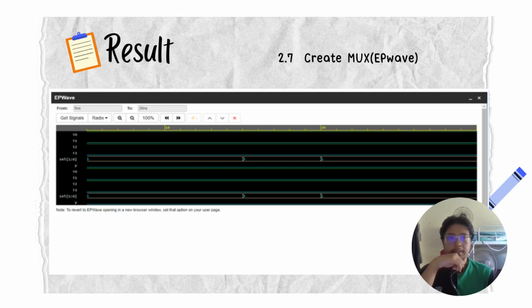We see the input signals I0, I1, I2, and I3 and the line that instantiates the MUX example module. This also includes the MUX example module output signal Y. This also sets the input values, iterates the simulation six times using random selector values, and displays the inputs and output using the monitor statement. That's all from me. Thank you.